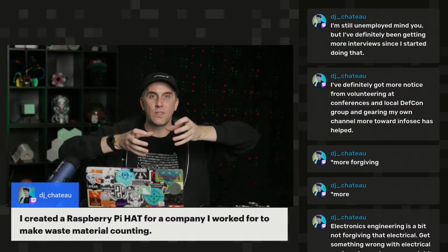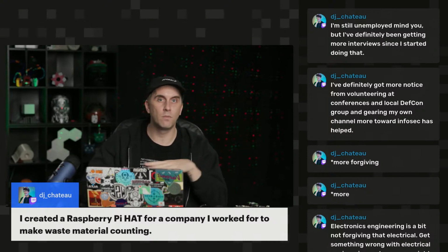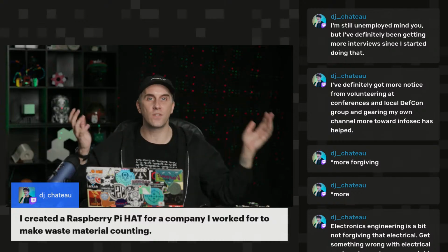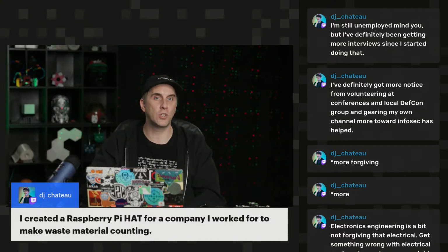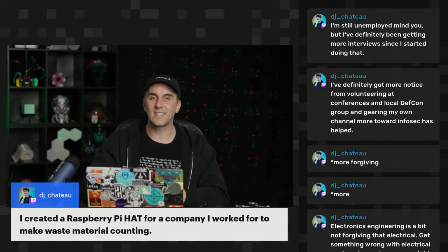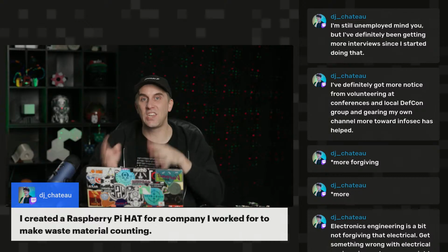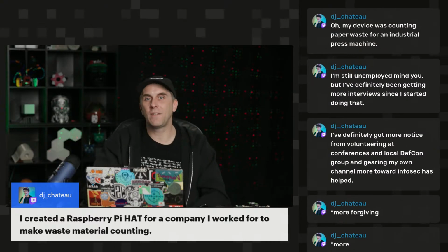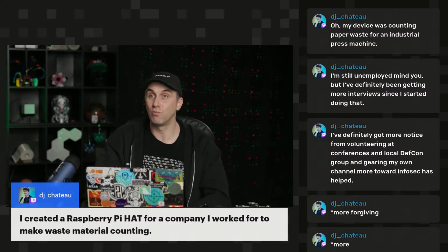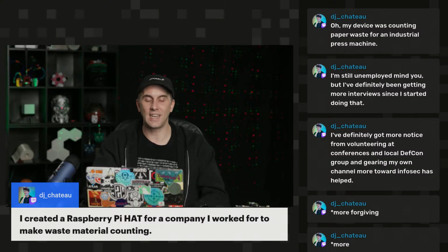If you just flipped it though and had that green side on the bottom, then suddenly it needs to do maybe 2 green layers to get that color, and then the rest of the entire cube is black, and it only purges the filament maybe twice or something like that. So depending on the way you slice these, it can create a ton of waste. And if you're not paying attention, you can really make it so it's almost 50-50 material and waste. So if you're trying to be efficient with 3D printing material, getting control of how much waste you're generating is a really useful and interesting metric. And it's something that I think a lot of people will be interested in keeping track of.